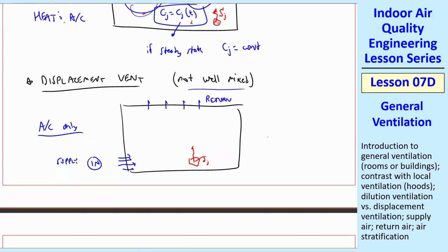The reason is because you have cool, clean air coming in, and the idea is that this air stratifies, so that you have warm air up here, warm air rises, and you have cool air down here. And then we assume there's a source that is buoyant. So the air tends to go up here, and you have some slow eddies moving back down to take its place. In the ideal situation, you wouldn't even have that. You would just have a clump of cool air that rises slowly.